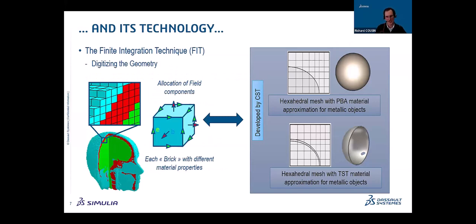Regarding the technology itself, the time domain solver, as well as the particle in cell solver that I will also discuss during this session, is based on the finite integration technique. The finite integration technique you can roughly see as a generalized FDTD method. The main difference is that we are solving Maxwell's equations in their integral formulation.